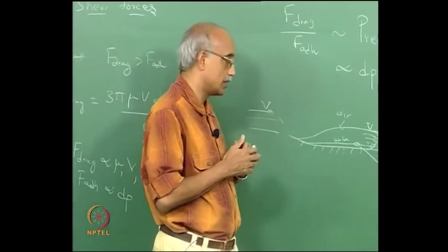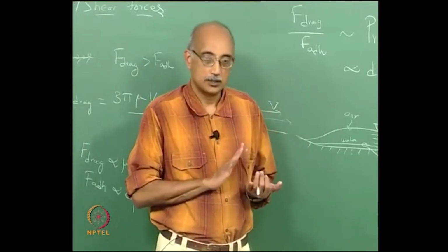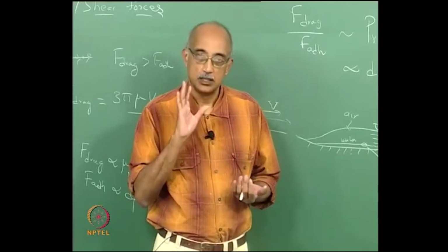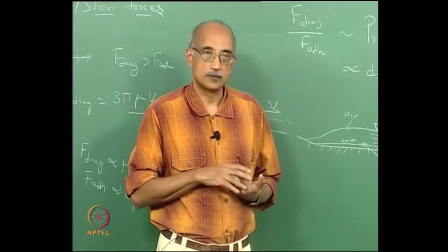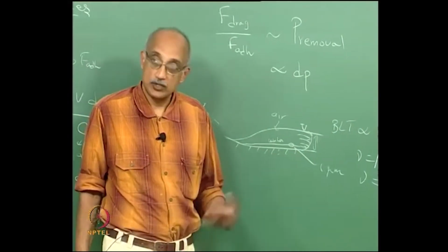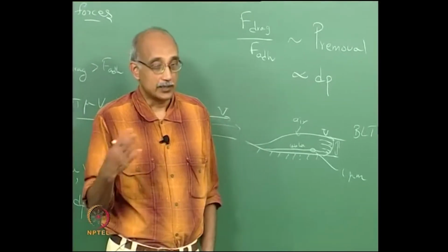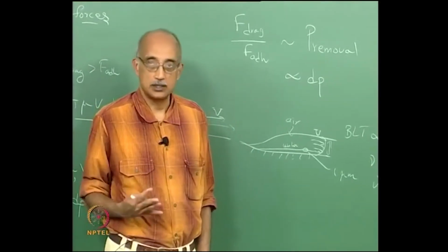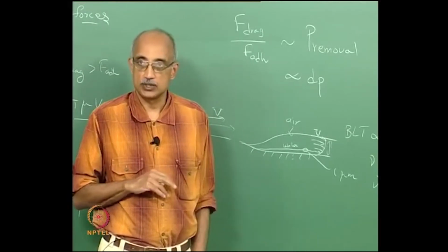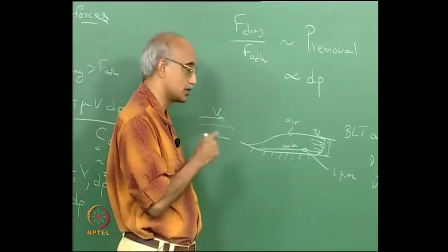So here in high pressure spray cleaning, you specifically employ pressures that can get you hundreds of meters per second velocity of the liquid flowing across the surface. When you do that, the boundary layer is virtually absent, and you can even remove submicron particles from surfaces. The downside of it is, at that kind of pressure, at that kind of flow velocity, you can actually start cutting the surface. In fact, high pressure water jets are used to cut metals. So you have to be very careful when you use these high pressure sprays.